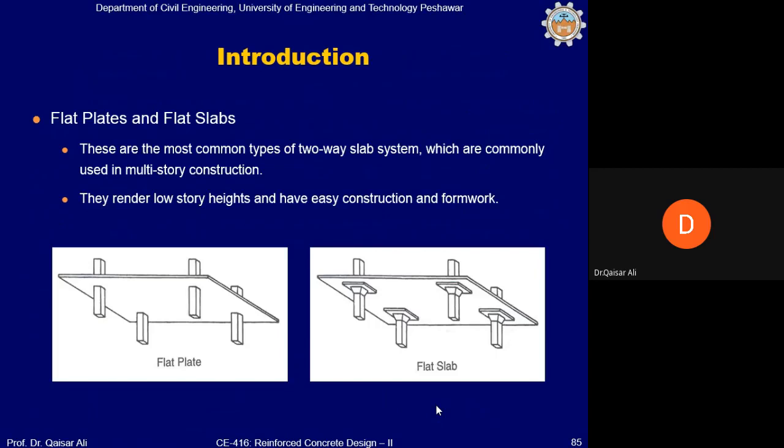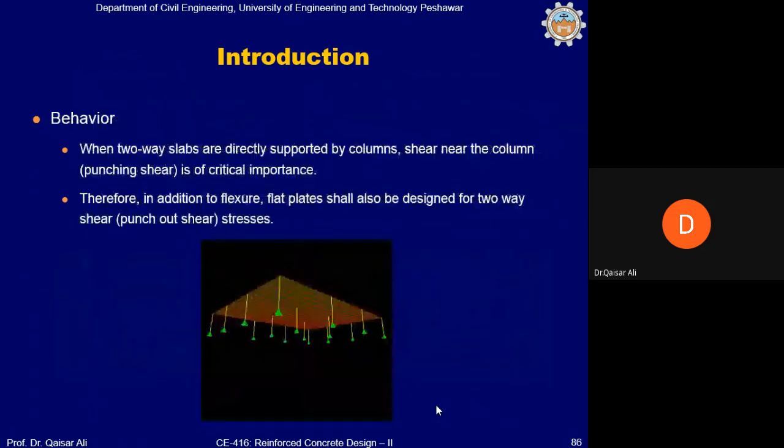We have discussed the background of the use of flat plates and flat slabs as an alternative to slabs with beam systems. Their advantages and disadvantages have also been discussed. The problem of punching shear is more or less similar to a case when a piece of paper, for example, is supported on paper pins. You know that paper pins can make a hole in the piece of paper.